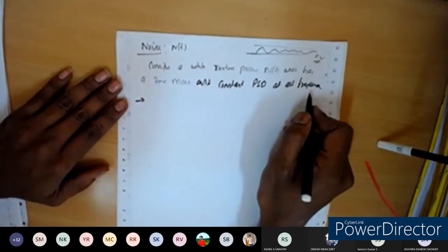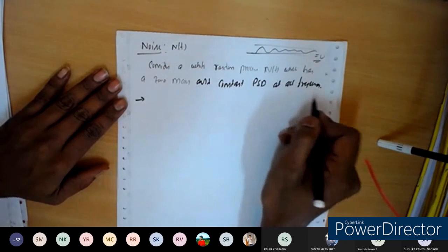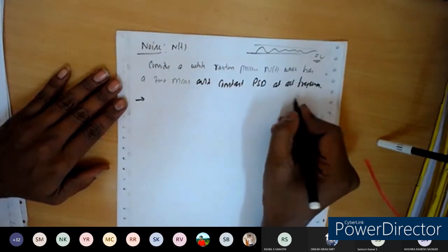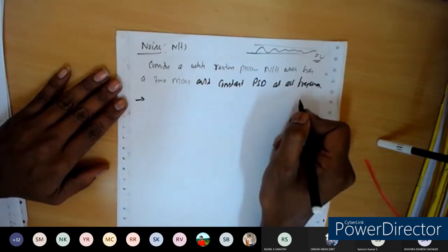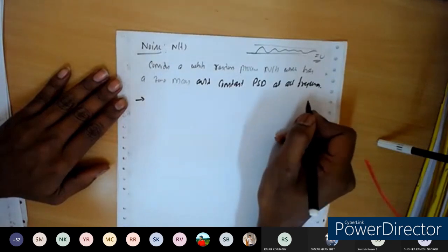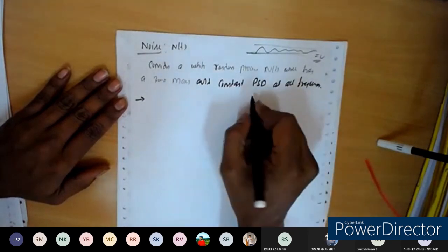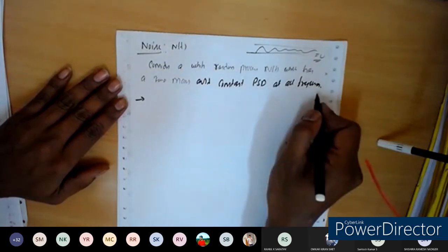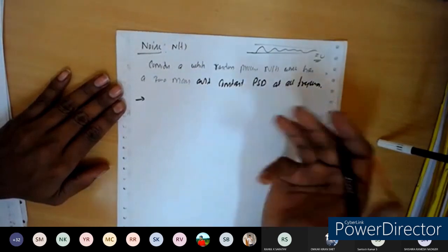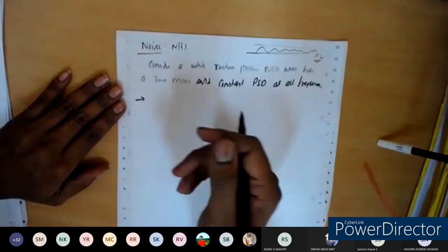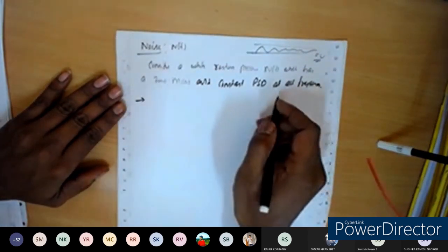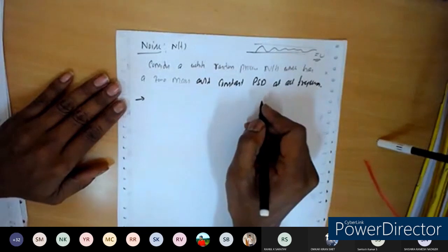This is for the frequency range up to 10 to the power of 12 hertz; it will be constant here. 10 to the power of 6 is mega, 10 to the power of 9 is giga, and 10 to the power of 12 is terahertz. Up to 1 terahertz, the power spectral density of the white noise will be constant, and that constant value will be some N0 by 2. When you model the communication system for designing the receiver, you assume some parameters, and based on that the power spectral density of the white noise will be defined.